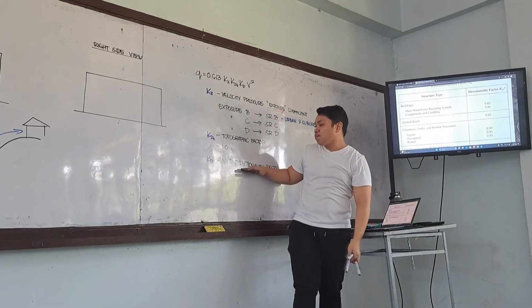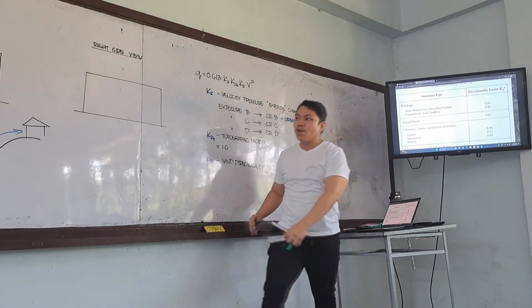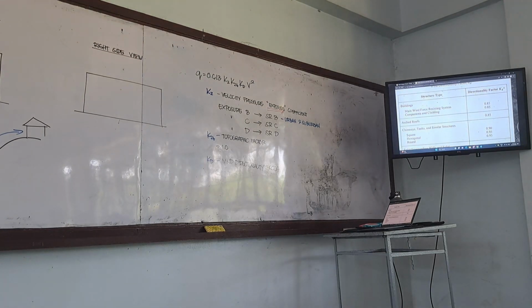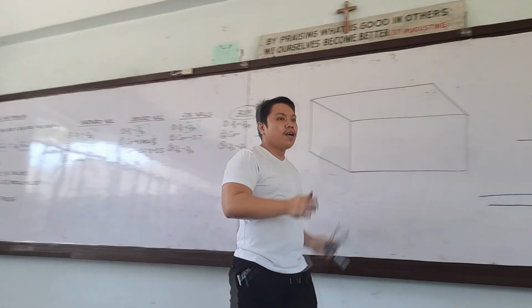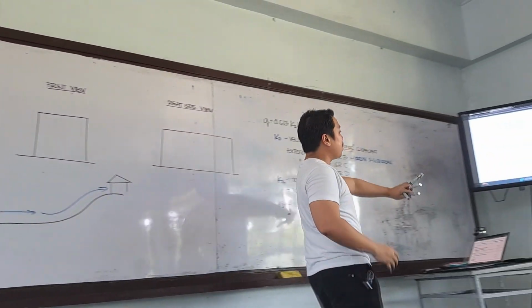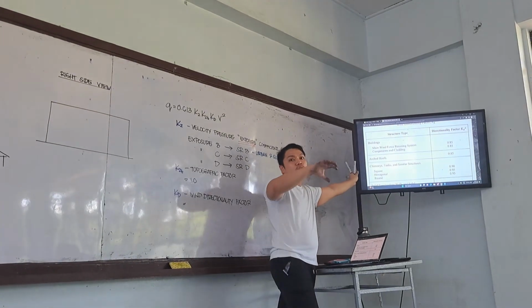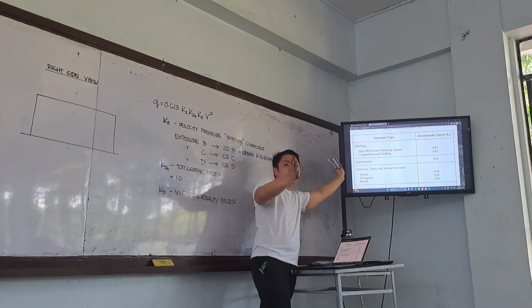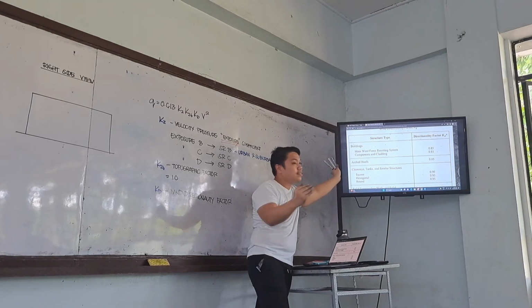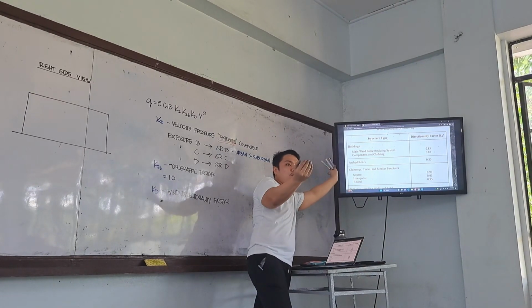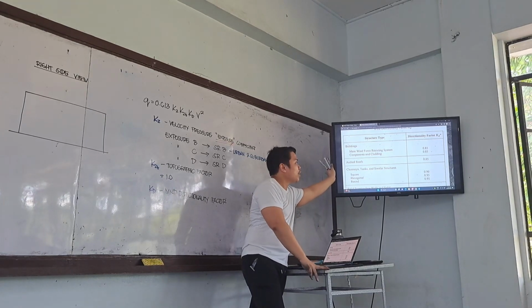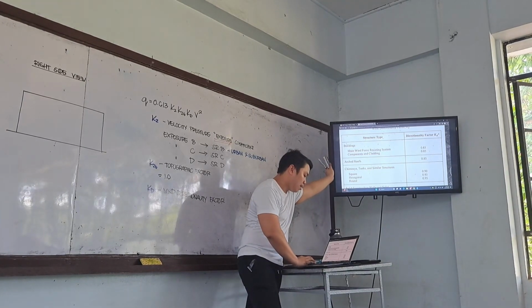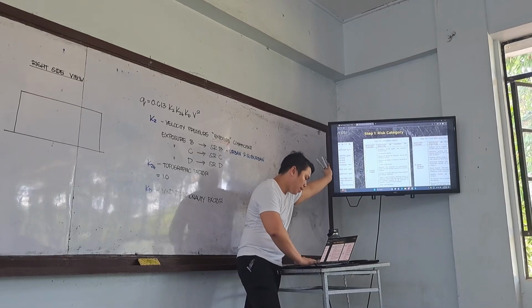That is from the keyword, wind directionality factor, which is our directional procedure. The wind flows from your windward wall in four directions, transferring from the windward side to your leeward and side walls. For our building, since it is closed on all sides, the wind flows easily from the side walls to the leeward wall. Compare that to our other structures.